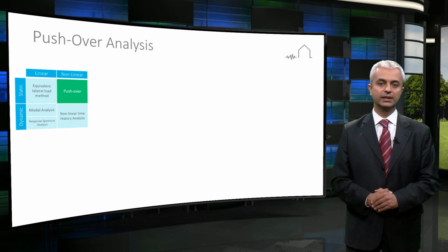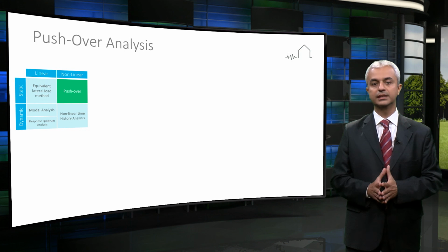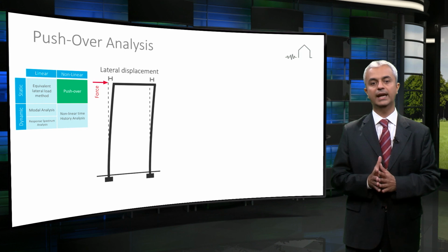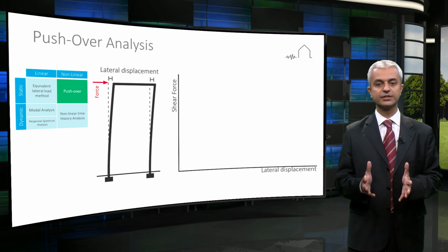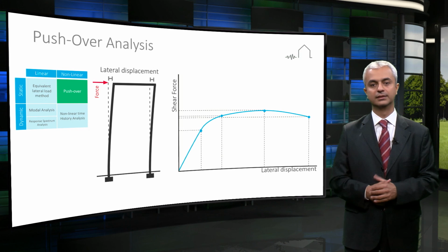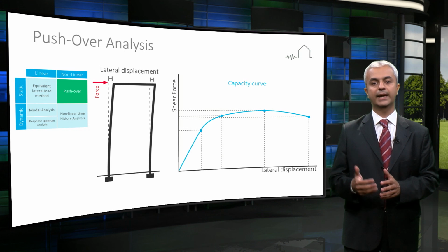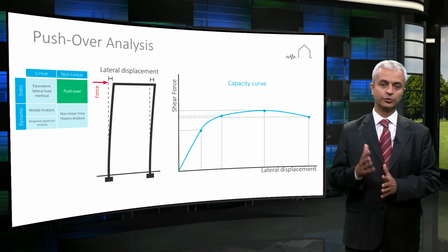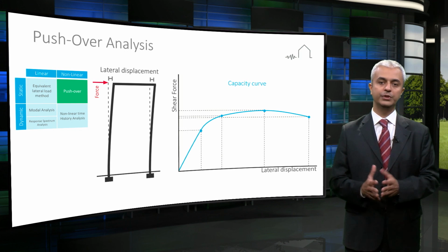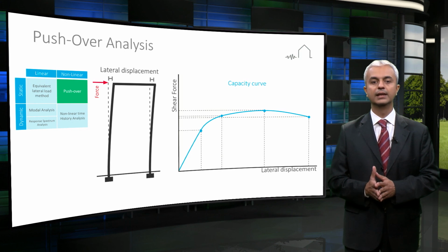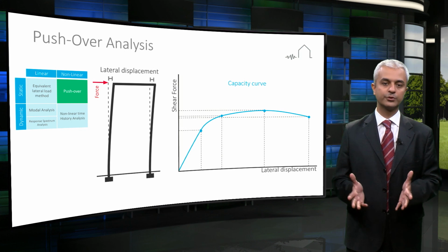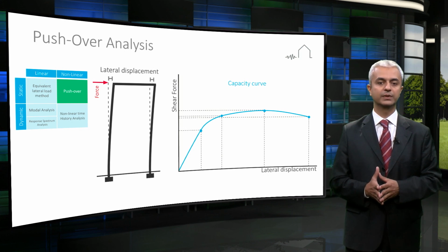A similar static loading is used together with nonlinear analysis in case of the pushover analysis methods. The structure is forced with unit forces acting in the shape of first mode, and the locations of plastic hinges are found iteratively. The final result of the pushover analysis is the capacity curve, which gives the actual performance level of the structure. If the structure is irregular or tall, which means that contribution of higher modes becomes critical, then modal pushover analysis should be applied. In this case, not only the first mode shape, but also higher modes are used like with the modal analysis.